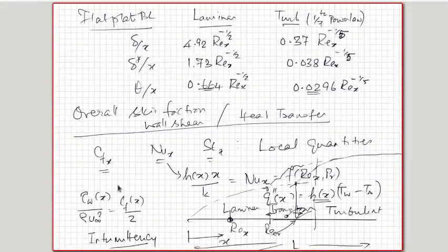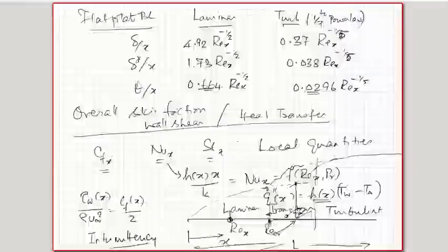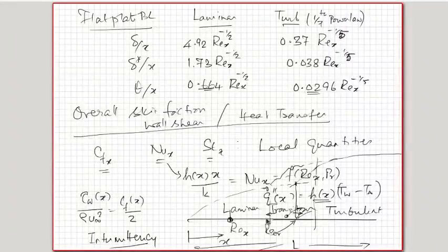So you never can make a very perfectly smooth plate for any experiment. Whenever there is a plate, it always has some level of roughness depending on the process by which the plate was actually manufactured. So if you look at it microscopically, there would be this kind of a structure, and there would be some things which are bigger than the others. Those bigger ones are the ones which introduce the larger disturbances and therefore lead to transition earlier.